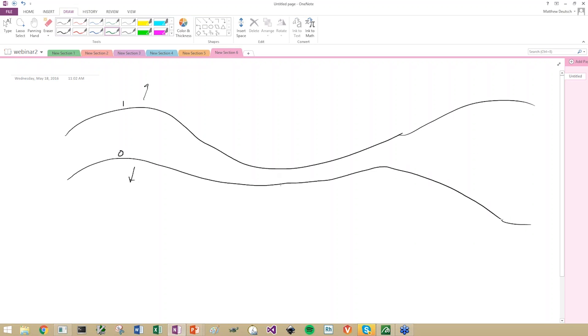What you would do if things pinch together, and you don't want these sorts of things being projected to exactly the same z values, is I would supply a representative top surface instead of the actual top surface, and this could simulate a sort of erosion in this particular case for the z values. So by supplying a representative top surface, I'm able to have that sort of control that you're asking for. Great, thank you, Matthew.